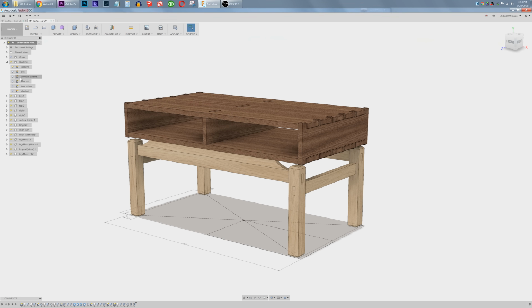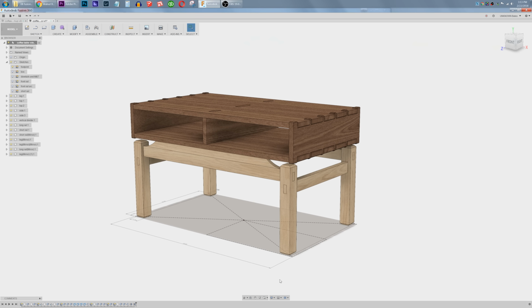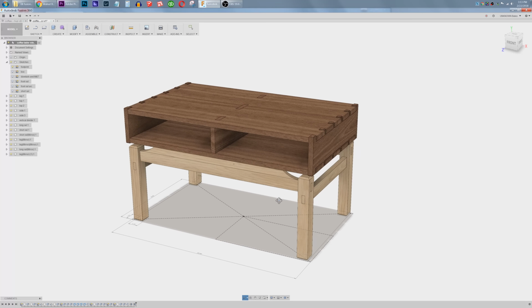So I've got the footprint sketch activated, and I right-clicked and said show dimensions. So now I can go back to my very first sketch and change this dimension to say, I don't know, maybe I realized that I don't quite have 36 inches of available space. Let's just say we have 33 inches of available space. Instead of modifying everything that I've already done to reduce 3 inches from the total length, if I just type 33, press enter, everything should update. And there you go. Everything updated accordingly because all of my sketches were fully defined. And that is one of the very amazing benefits of parametric modeling.